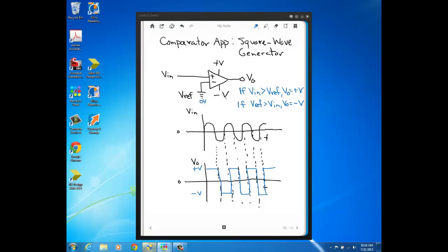They don't necessarily have to be equal, but with some op-amp ICs, you cannot make the minus power source 0. You couldn't just ground the pin of the IC that this corresponds to.